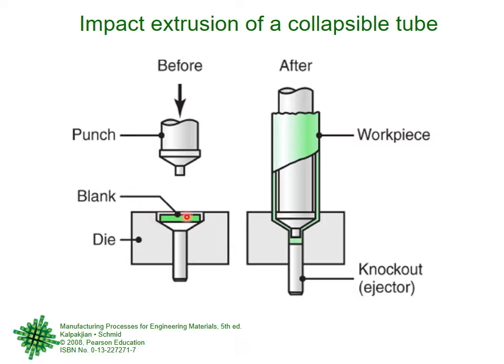So you have the die, you have the bottom die, right? And you have the blank material, which in normal extrusion is called a billet material. And you have the top die, which is the punch, right? And here it is just an ejector pin. I'll tell you, it is just like you did in casting. So you come with a boom, right? One hammer blow.